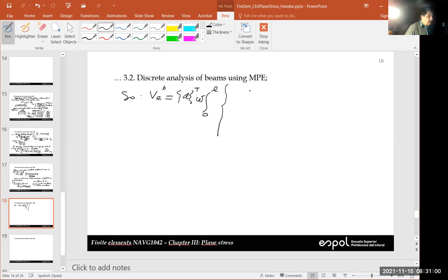And now I'm going to remember these polynomials. These polynomials are 4 polynomials, and we have to integrate in X. I'm going to skip the hat because this integration is in the local reference system. So each one of these 4 elements is divided by 1 over length cubed. And in the class notes, we deduce that this is 2x cubed minus 3x squared L, I'm sorry, plus L cubed. The second one is x cubed L minus 2x squared L squared plus x L cubed.